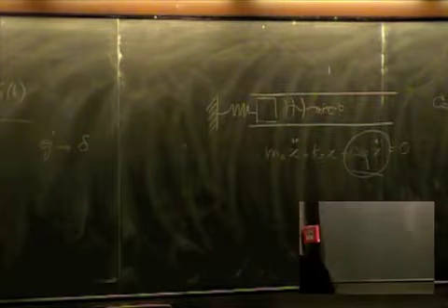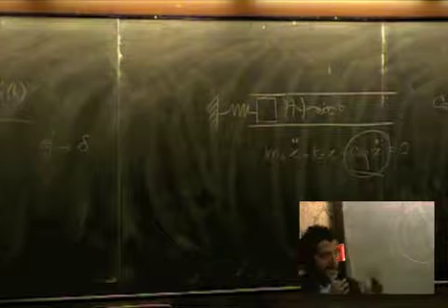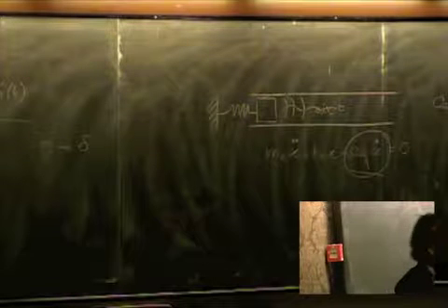But as you know, it is not easy to control the damping in a structure, because generally damping is something that we can add, but we have a certain difficulty to control. For example, if I want a higher damping at the center frequency or a small damping at other frequencies, we know, if you examine just the single degree of freedom resonator, that when you introduce damping, the damping has a good effect around the resonance. But at high frequency, having a high damping can be even worse.